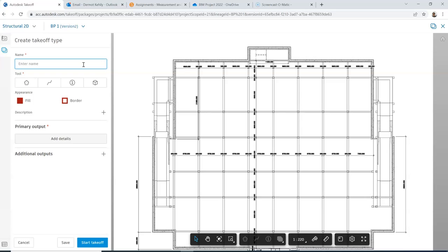And I believe there's a number of beams here, and it's just beams that you've been asked to take off in 2D. For the few beams, you can look at the sections, you can look at the details, etc. But for me, it's beams, and there's a number of them. There's a 500 by 900. And in fact, let's start with that one. Let's just do one, and then we can duplicate what we need. So it's 500. You can even put 500 wide by 900 deep, and of course they're millimeters.